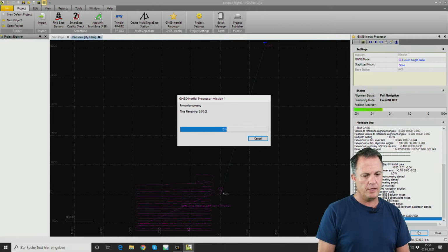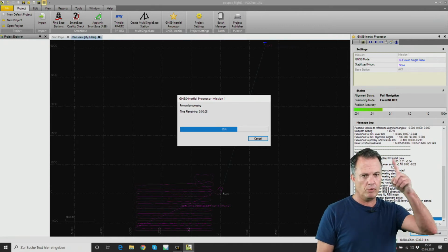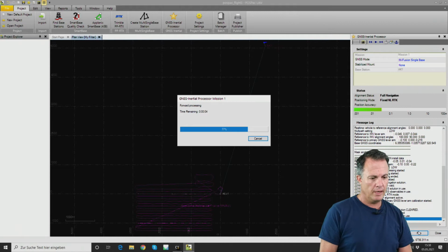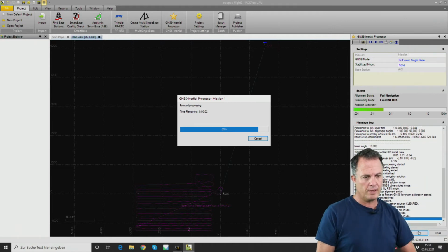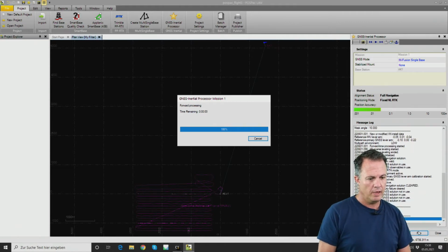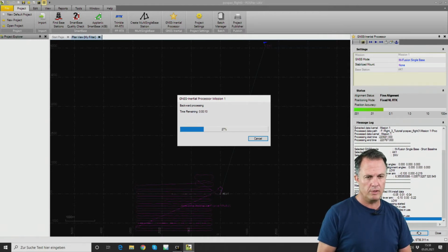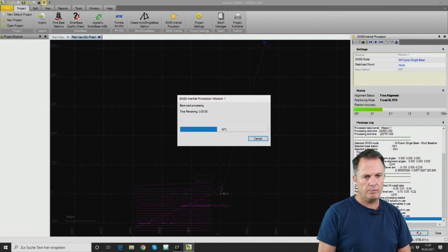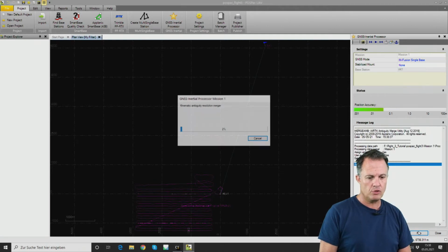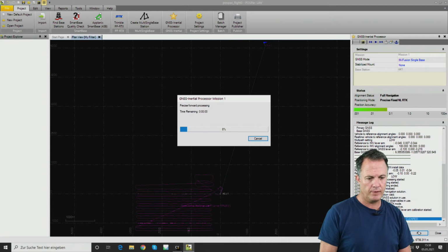While this is doing the processing, you can monitor the accuracy here, and there are some results displayed on the right side. And actually what we can expect is a 1 centimeter, 2 centimeter, 3 centimeter PPK average accuracy. And once the process is completed, the last step is to export the SBAT file, a text file which we will later need in the CloudStation software.